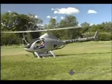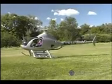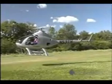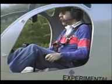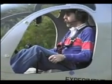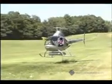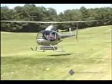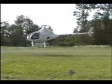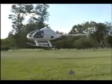With traditional fixed-wing aircraft, the faster it moves through the air, the more lift it produces. But a helicopter can fly without any forward movement at all. It can hover. Rather than moving the whole aircraft through the air to generate lift, helicopters use rotary wings. It is this ability to separate the aircraft movement from the generation of lift that allows a helicopter the advantages of vertical takeoff and landing. Helicopters don't need runways, and forward movement isn't required for the helicopter to maintain maneuverability.